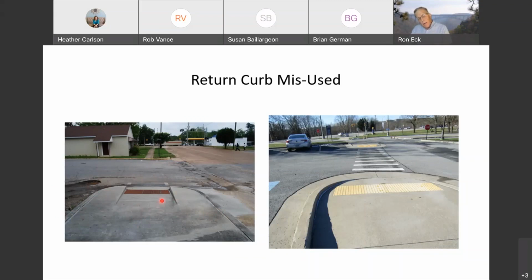So we do not want these vertical edges or lips or steps here because these can trip all pedestrians, even able-bodied pedestrians. To me, I'm not sure why they didn't just ramp down this entire end of the sidewalk here with a detectable warning surface across the entire width of the sidewalk. Would have been a preferable design, in my opinion.